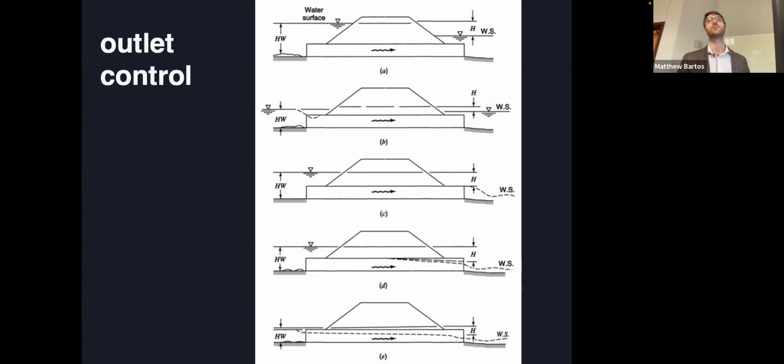Yes. With some of these, will a culvert usually be either outlet control or inlet control, or does it also depend on the scale of that? It could, yeah, it could depend on the discharge as well. I'll have to think of an example where that could happen, but it's essentially whether you achieve critical depth at the upstream end or whether it's fully submerged. So I can imagine, if you increase the discharge enough, you may end up with the culvert just being overwhelmed and being pressurized on both sides, but it would operate under inlet control for a different discharge. So that is possible, yeah.